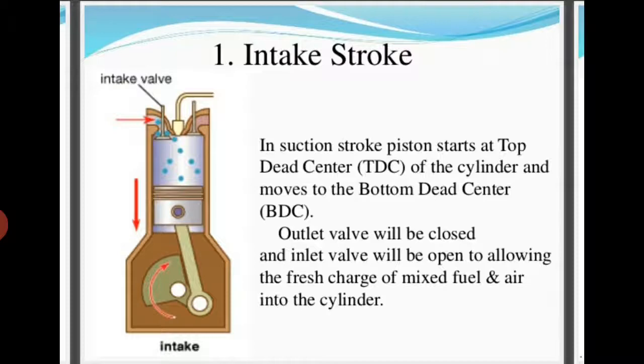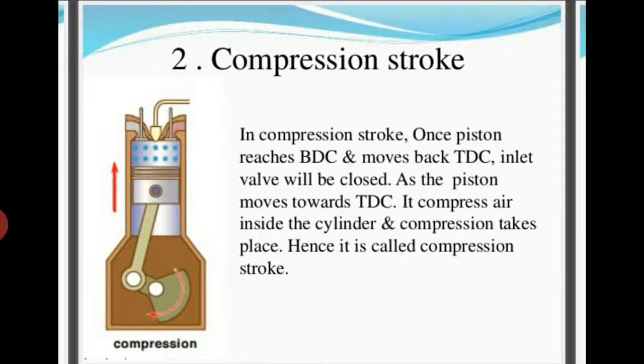Now as you can see in this slide, the inlet valve is open. From here air enters the engine cylinder, and air keeps entering till the piston reaches the BDC position. When the piston reaches the BDC position, the inlet valve will close. Now you can see the next stroke, the compression stroke.